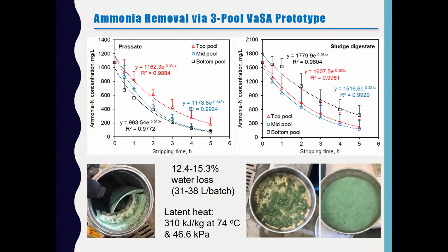We got similar results as the single pool vessel system, efficient. And we collected ammonium sulfate crystals. Originally, the absorption column was cooled, so we got chunks of ammonium sulfate in the column. Later on, we poured the solution through sieves to collect the crystals.